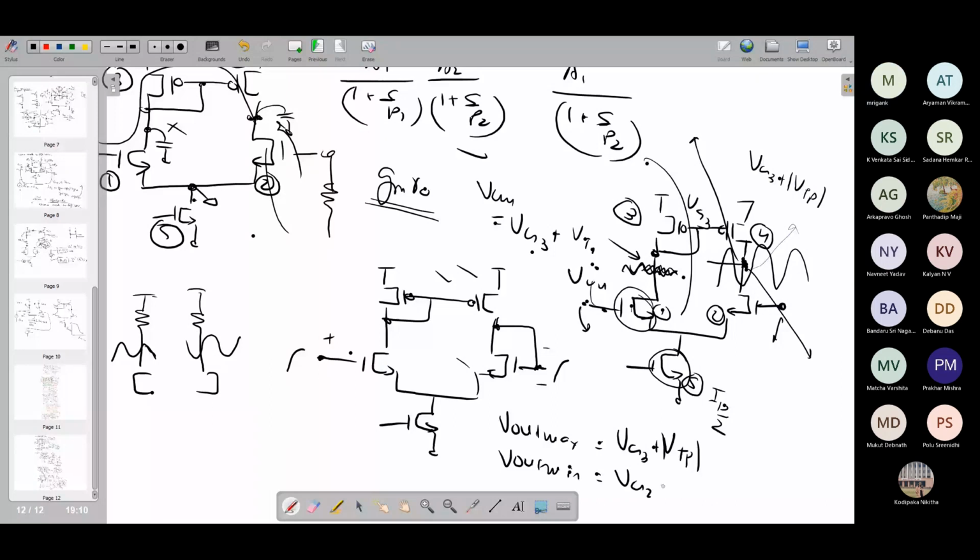minus VT2, right? But is that the thing we are going to look at? What we need to see is with respect to the DC bias point. This is of course the maximum and minimum achievable value. That is true. But what if I ask you to find out the maximum symmetric swing? What will you do? VG2 in turn depends on the M5.